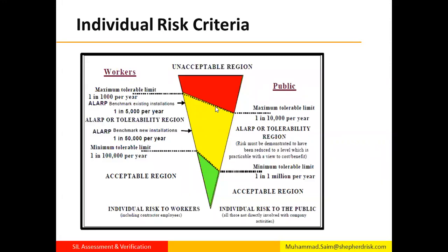Can SFF be calculated after performing FMEA? Yes, we need to know various failure modes, and we need to know the diagnostic coverage, and we need to know which of the failures are detected and which will remain undetected.